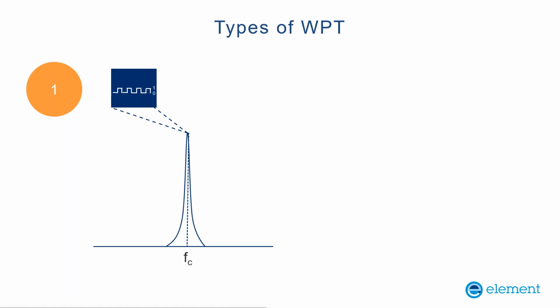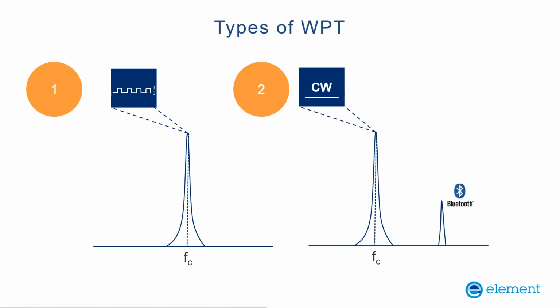There only needs to be one bit of data, but if there is one bit of data, then it is categorized as a type of WPT, as opposed to the other type where the frequency used for the transfer of the energy itself is just a CW signal, it's just a carrier wave. The information about what the load is doing, its status in terms of battery level and this other information is typically provided through other types of communication.